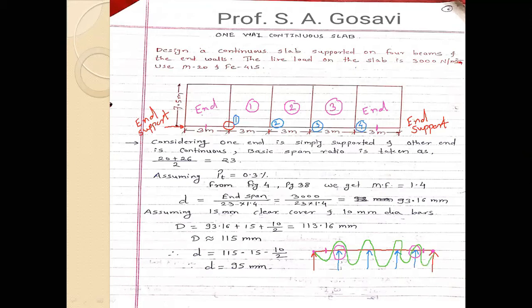Okay, so this is the bending moment profile. If you see, this is your positive bending moment, sagging. This is also positive bending moment. Here it is also positive. This is also positive. This is also positive. And all the hogging bending moments are negative bending moments. And you notice that you are getting the hogging bending moment at the support only. Here where we have provided the support, at the support the hogging bending moment is there.